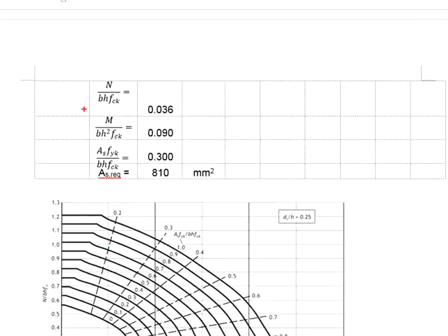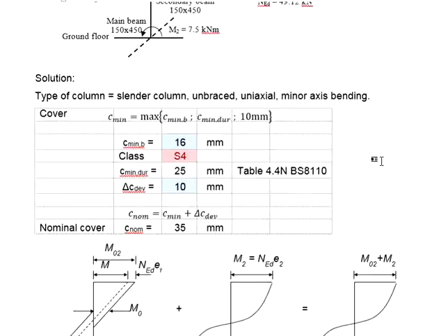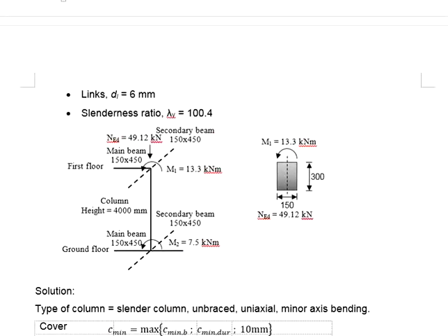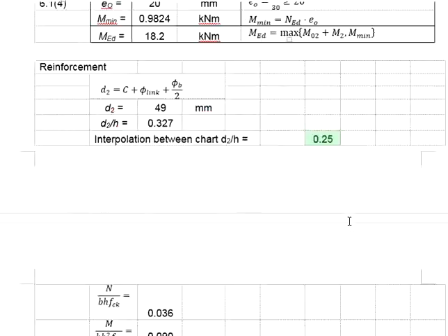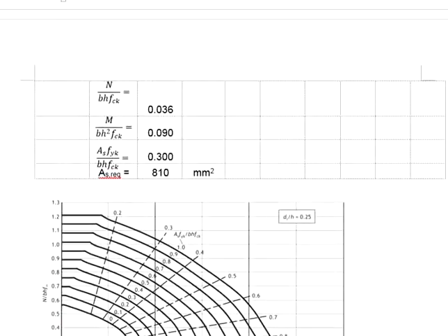And also calculating the x-axis of the design chart for the column, you have to be careful with the h square. You need to choose the right value, especially when the column is in rectangular shape. Getting the wrong h will lead to mistakes in the calculations.